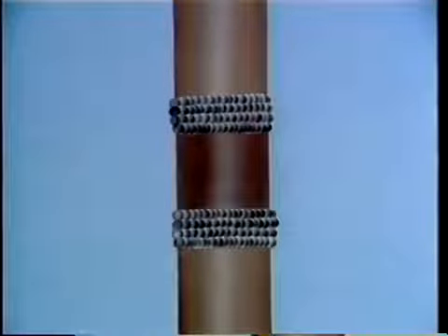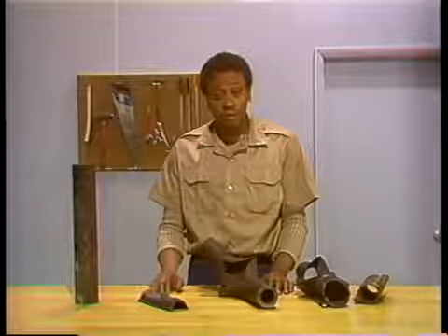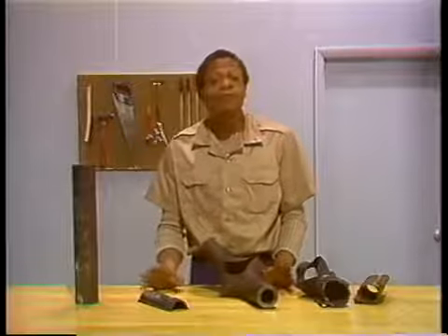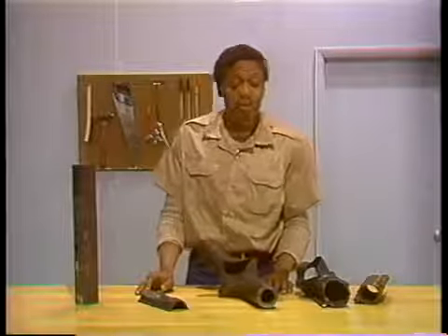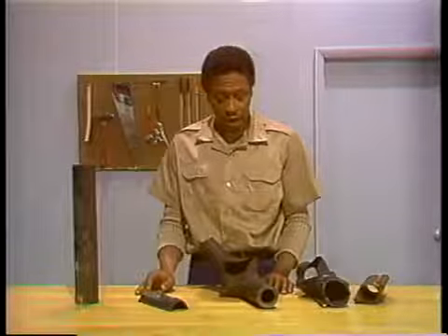The best and most sure way to repair failures and deformities is to replace the damaged section of tube. Although this is the best way, it isn't always possible because it's time-consuming. There are several other methods that are used when there isn't enough time to replace a section of tube. These are cladding, closing a rupture, and window repair.